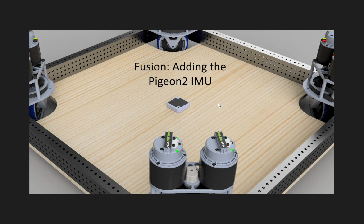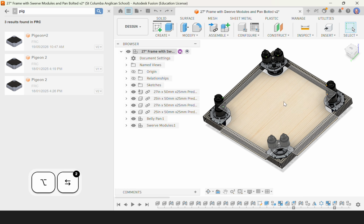We're going to insert the Pigeon, which is an inertial measurement unit, a device used for measuring angles of our robot, into the design. We're going to project through the two holes from the Pigeon into the belly pan, create the holes in the belly pan, and then insert 2 bolts to bolt it in. So here's our frame so far without the Pigeon.